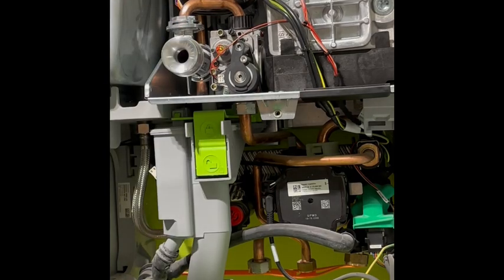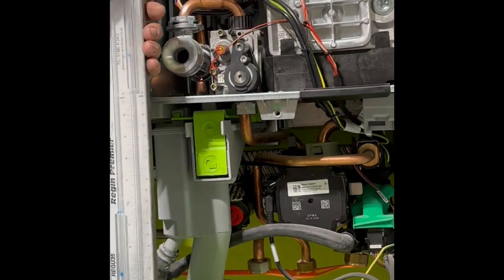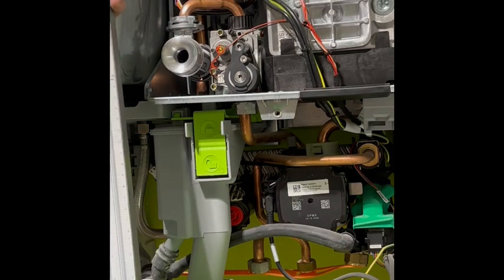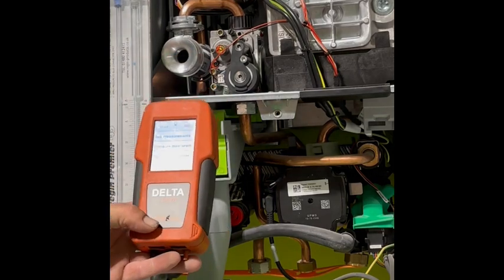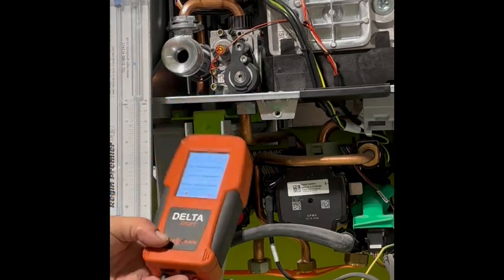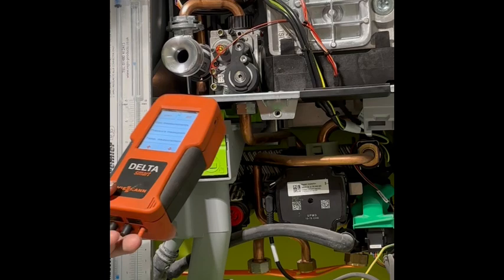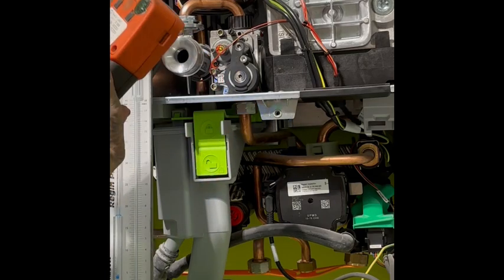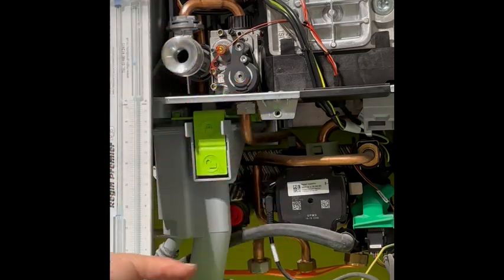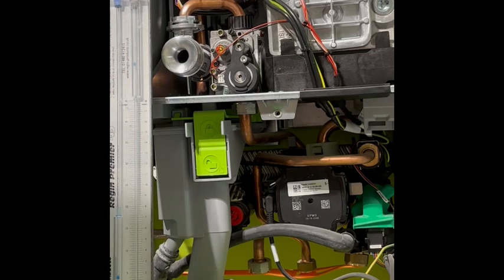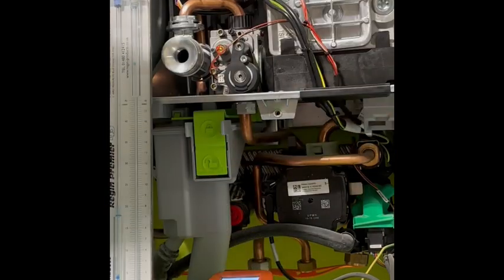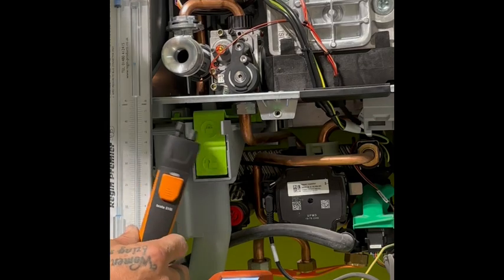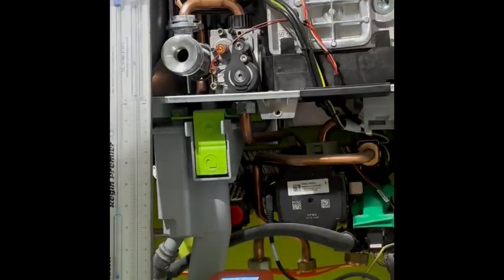So I always find personally, when I'm looking for an ignition fault, that using a gauge like that or a water gauge is far more responsive than using an analyzer. Whether it be one of these is a Riazzi, I've got Kane as well, I've got Testo. They all seem to lag a little bit, the analyzers do. However, the Testo Smart Pros are a lot faster. They do respond a lot quicker.